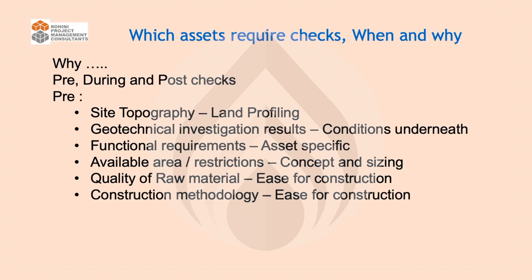Coming on to the next point is quality of the raw material. That will make your life easier to understand what construction methodology can be used or what is the quality of the material which is available in and around or at that location. So obviously the cost is a guiding factor to that, right? So all this we study during the pre-stage, pre-construction.